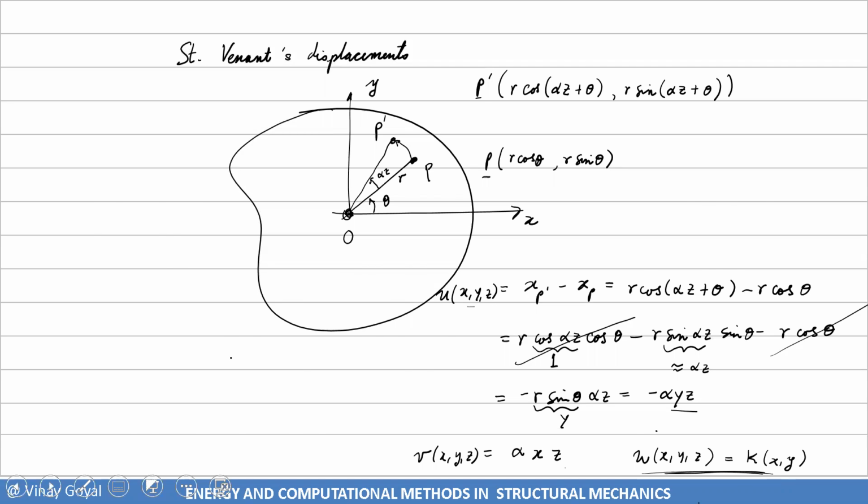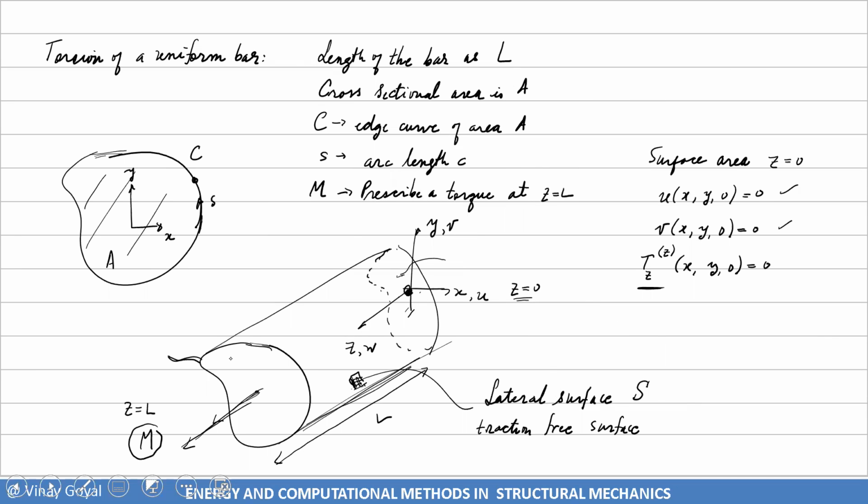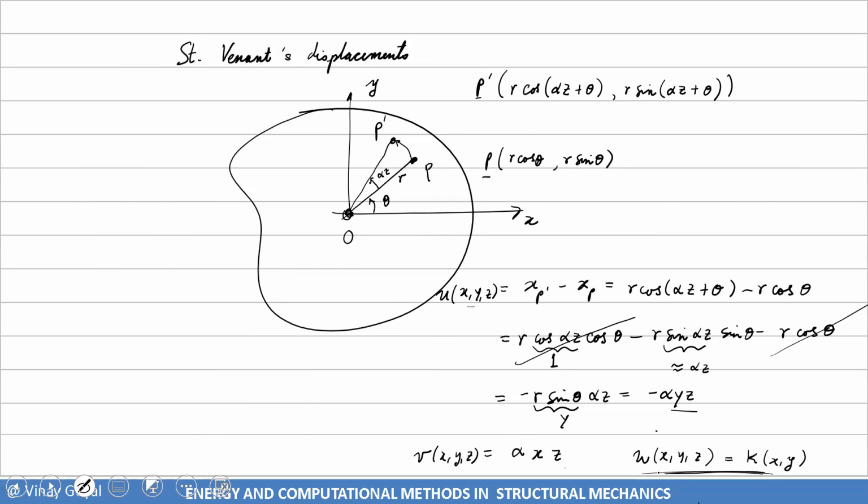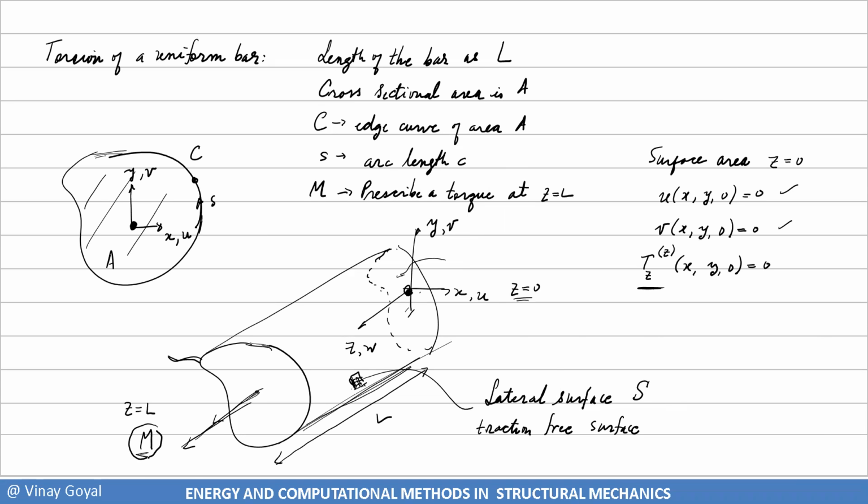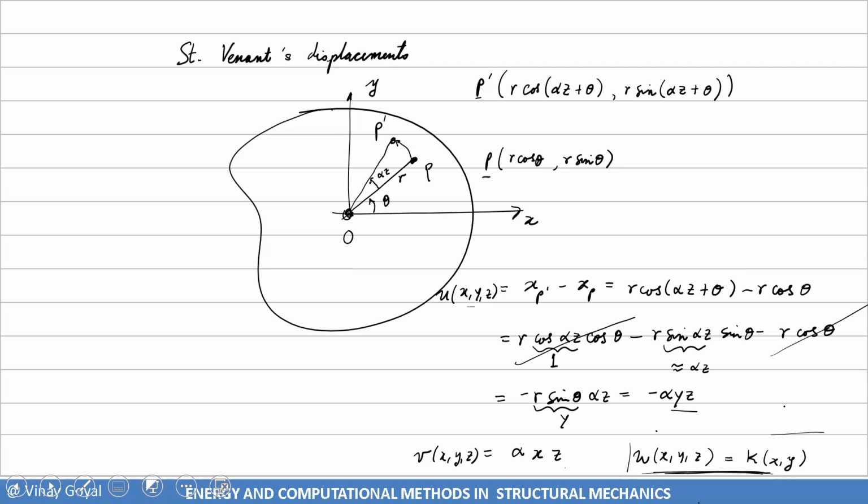So let's look at this physically together. U and V are really the deflections in the plane of the cross section. W is out of plane and describes how, when I apply a torque, that cross section can come out of plane. That's what this function is doing for you, enforcing that. Hopefully that makes total sense. Now I also want to comment that in this theory, I'm applying a load m, but here alpha is unknown as well.